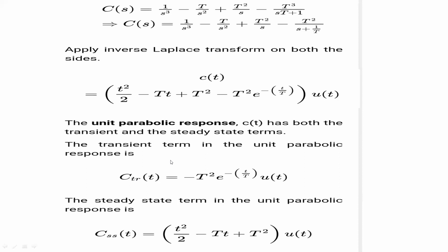So from these responses, we can conclude that the first order control systems are not stable with the ramp and parabolic inputs, because these responses go on increasing even at infinite time. The first order control systems are stable with impulse and step inputs because these responses have bounded output. But the impulse response doesn't have a steady state. So the step signal only is widely used in the time domain for analyzing the control system from their responses.